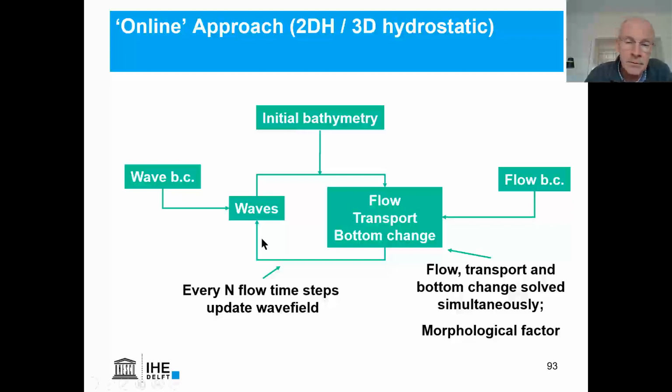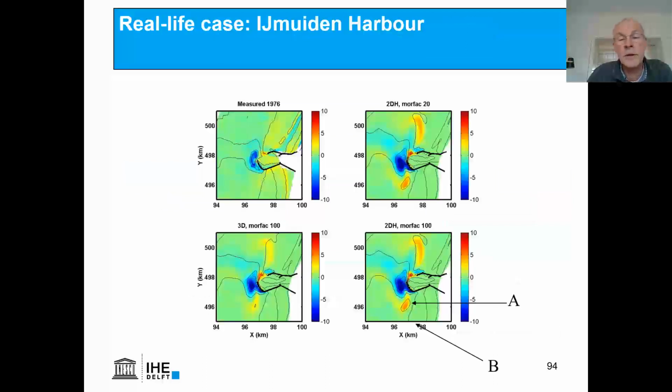In fact, what we're also doing is we're elongating the time. The tidal cycle, so instead of simulating 700 tidal cycles in a year, we may be doing only 7 cycles in a year. And continuously we do the updating multiplied by a factor of 100. That, you might think, is quite a bold step. Now let's do a test case here.